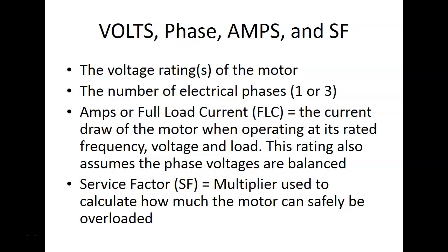They'll have 2 voltages on there. And you just can't run it, right? We looked at this the other day. You have to wire the motor for the voltage you're going to run it on. So it's just like our transformer, right? So what do we have to do on our transformer? We'd wire the primary of our transformer depending on the voltage that we're going to put in.